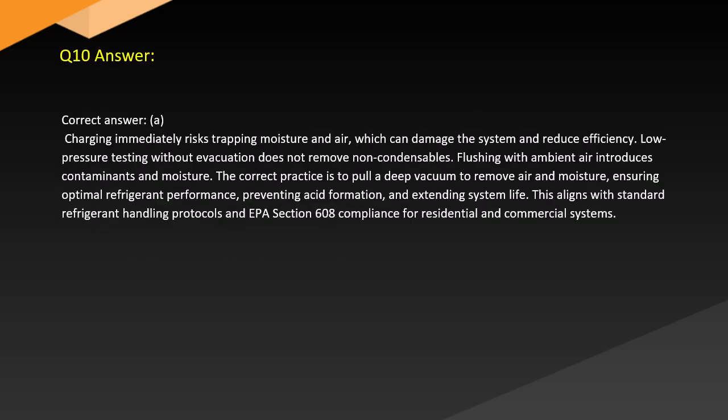Answer. Correct answer: A. Charging immediately risks trapping moisture and air, which can damage the system and reduce efficiency. Low-pressure testing without evacuation does not remove non-condensables. Flushing with ambient air introduces contaminants and moisture. The correct practice is to pull a deep vacuum to remove air and moisture, ensuring optimal refrigerant performance, preventing acid formation, and extending system life. This aligns with standard refrigerant handling protocols and EPA Section 608 compliance for residential and commercial systems.